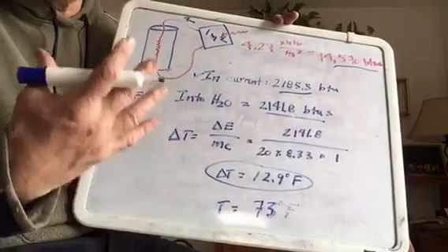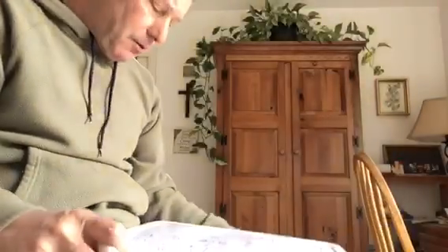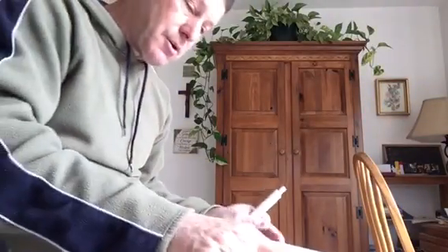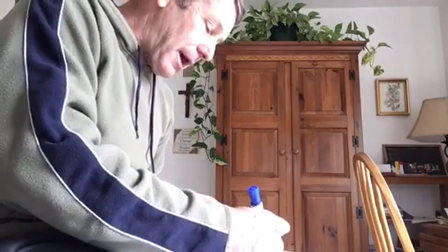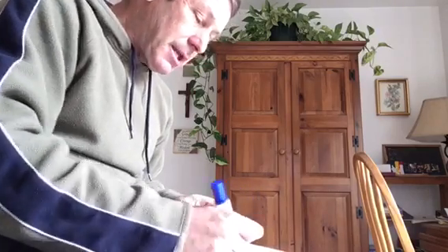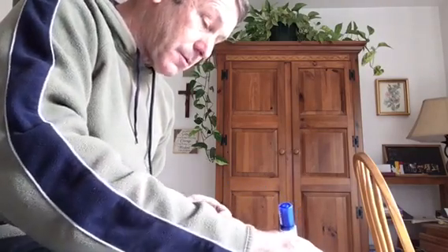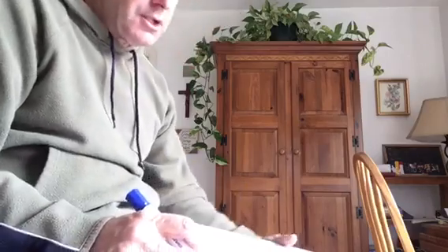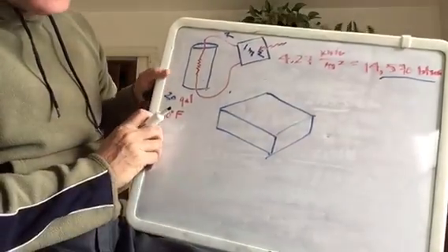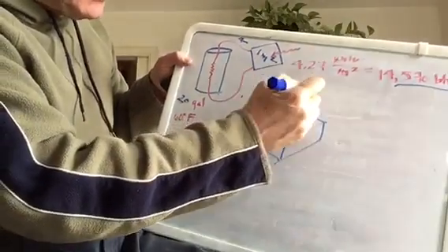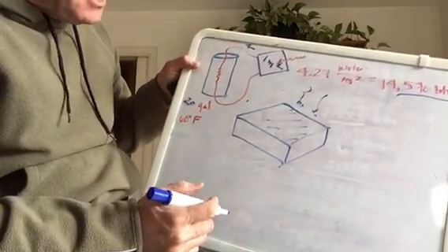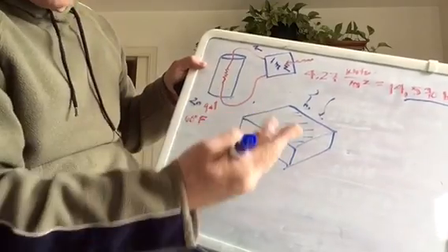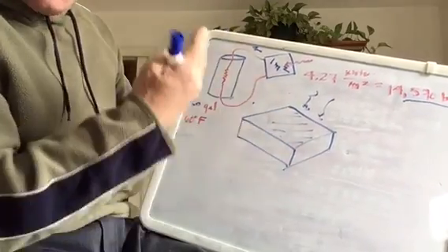Okay, what are alternatives? Do we have to do PV? Well, the other alternative that we talked about was putting that water in a black box, with a surface that is really good at absorbing solar. So again, we had something like that, a batch collector. And so the heat's going in here like this. This top surface is some sort of surface that's good at absorbing solar, and we're going to get some water in there. Well, we're going to lose some heat because of convection, and there's going to be emission as well,